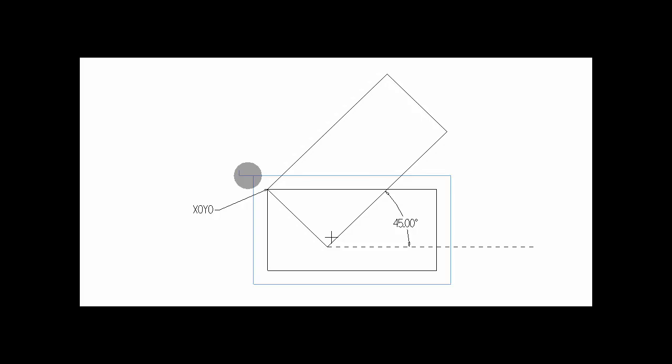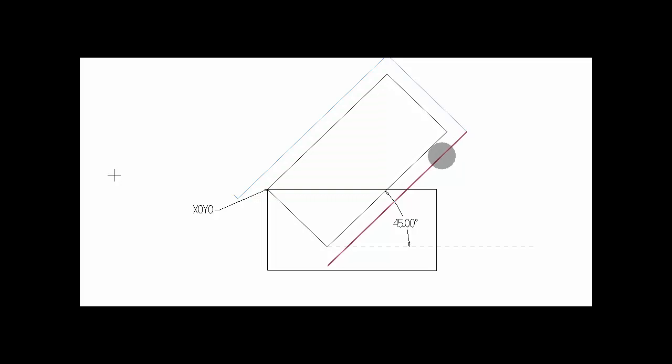Now I'm going to show you how to use the G68 command to rotate about this point, this origin right here, and use the same code that was used to mill this shape at the flat orientation to mill the shape at the 45-degree rotation. So that same code is going to make that end mill walk this shape just like this. So let's take a look and see how that's done.